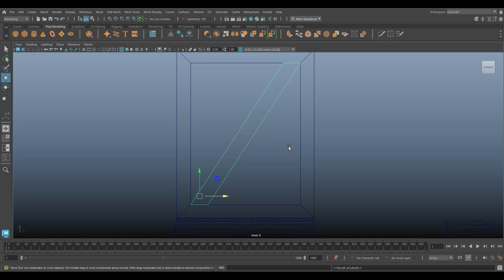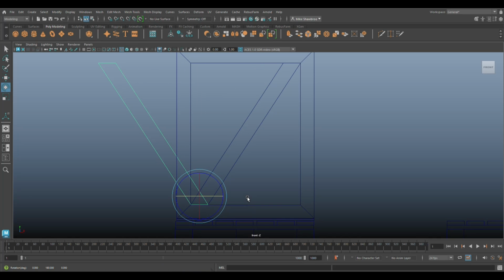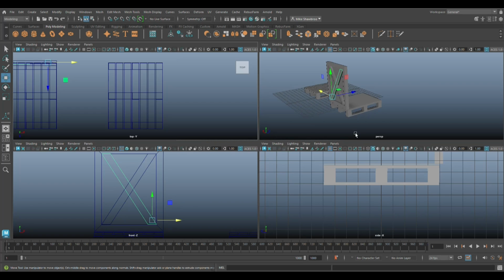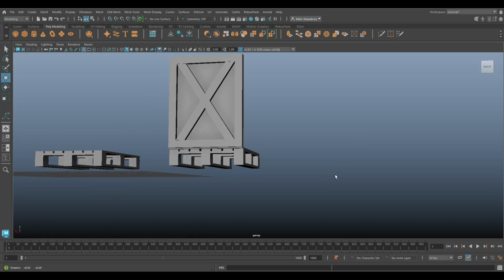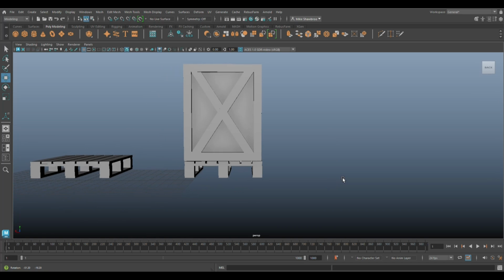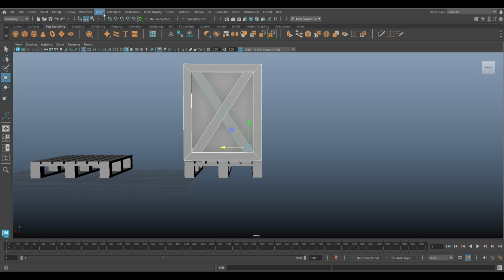We're going to go in here, we're going to grab it, and we're going to Control D to duplicate, E to rotate, hold down J, flip it around like so. Hit W, move it into that corner. So it gets something looking like this, right? And then what we're going to do is we're going to grab it. We're going to go to Mesh and Combine.